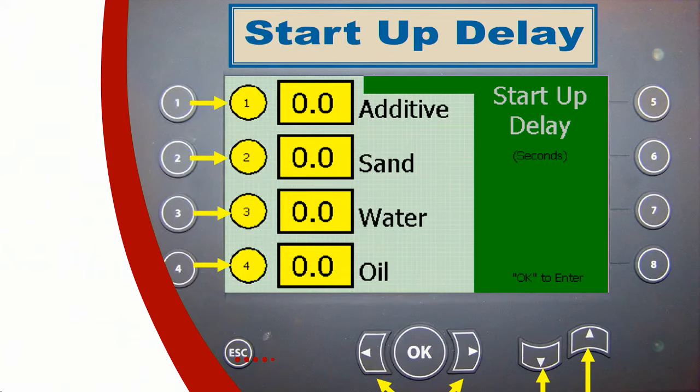The machines also have evolved, and they are much simpler to operate. So you get this large machine, it's a batch plant. Once you have everything set up, there's one button start. You push one red button, the whole machine sequences on and starts producing the slurry or microsurfacing. When you get done, you push that same red button, and everything sequences off so that you have a perfect blend of the material on the first part of a pour and the end of a pour.